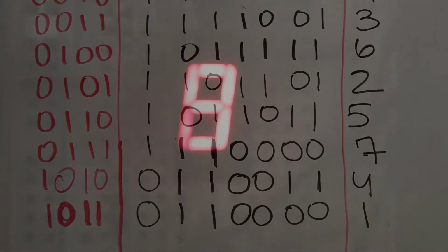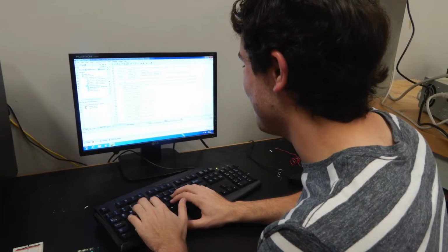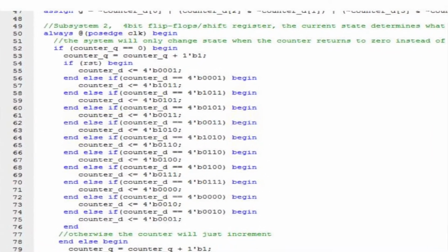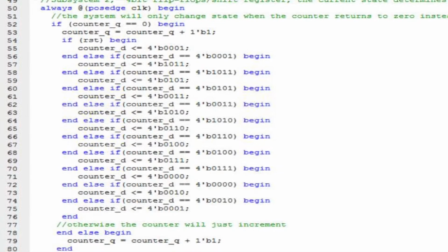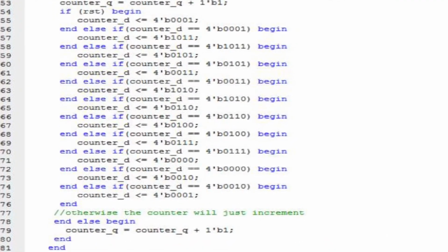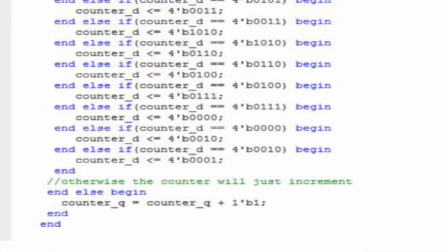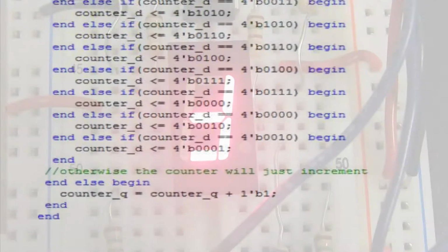During the lab, because the clock pulse was moving so fast and the state changed so fast as well, we couldn't read the number on the counter. So we control the state change by constructing a 25-bit counter that changes state whenever it hits 0, and we also add the code to slow the clock cycle down.